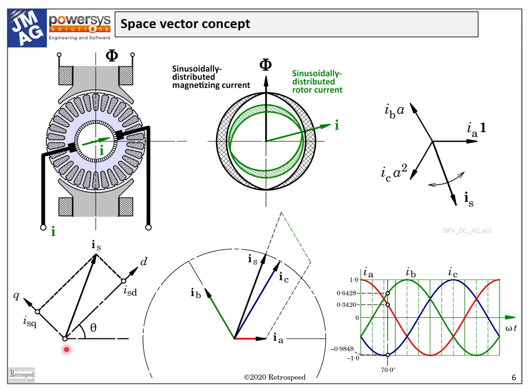For example, in an induction motor, we can orient it in such a way that the d-axis is aligned with what is called the rotor flux, or more precisely, the space vector of the flux linkage of the rotor circuits. This is what is done in Leonhard's field orientation diagram.